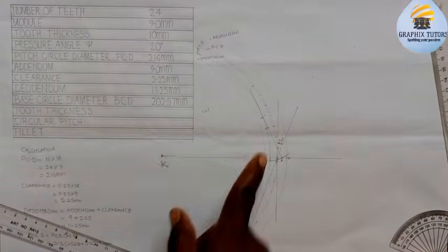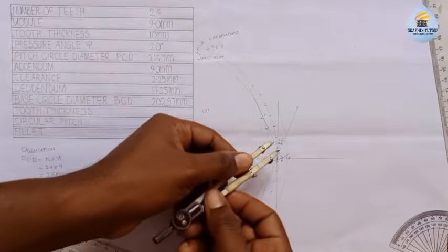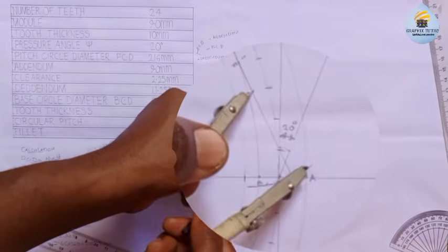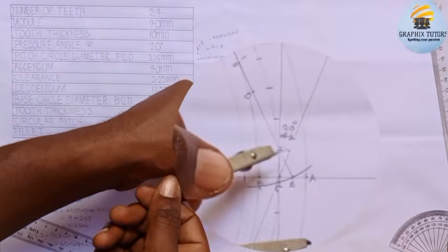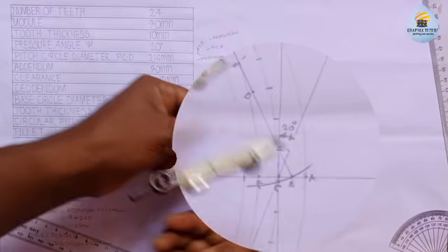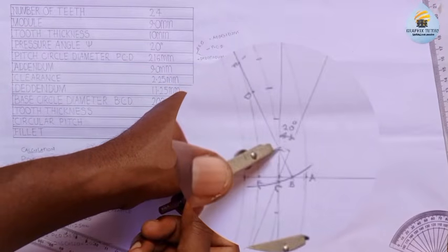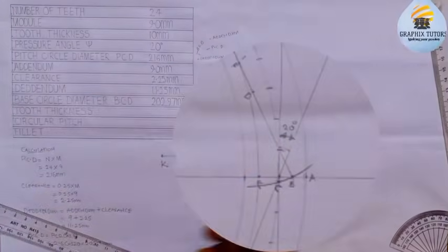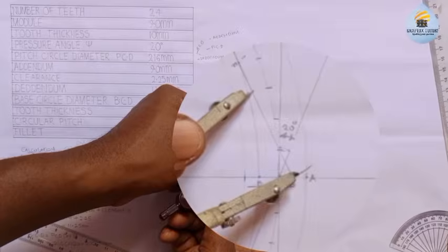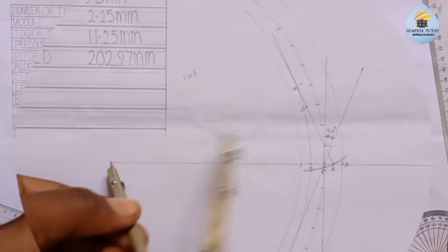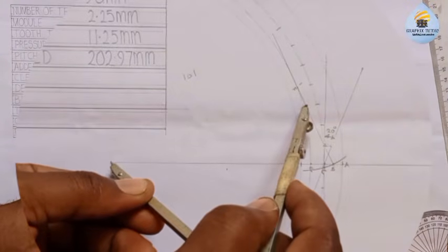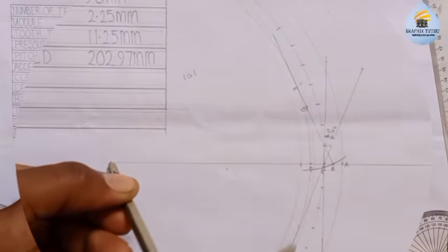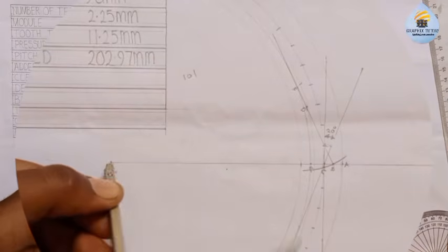Now let's start. Now, you know I got this arc from D. Am I correct? Look at it. I got this arc from D. Now I will place it. I need to close it up, right? So to close it up, I'll place it here on the other tooth thickness here, and I'm going to mark. And before I do that, I got it from this point here. So I'll place my compass at K, take it to what? To D here. You can see that? And I'll now draw another arc this way. I'll call that my radial arc.